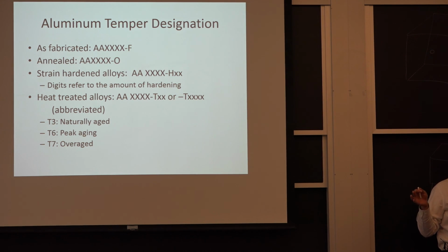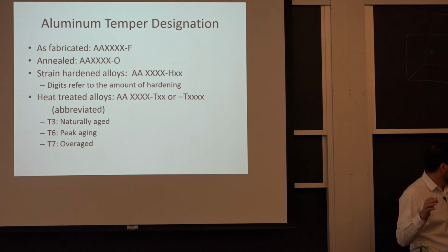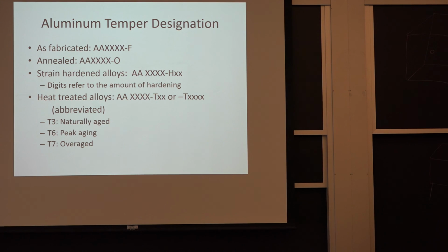This is a little bit in between with the aluminum, because we're including a little bit of the chemistry here with a little bit of the process. So this is really the heat treatment. Does it have a mechanical requirement? No. It's just a recipe for how to do it. So if you want to have minimum material requirements, it becomes part of an aerospace material specification. That's another kind. Or an ASTM specification that will have those minimums. Otherwise, you don't know what you're getting in terms of mechanical properties.